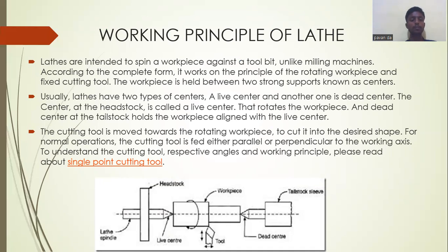The cutting tool is moved towards the rotating workpiece to cut it into the desired shape. For normal operations, the cutting tool is fed either parallel or perpendicular to the work axis. To understand the cutting tool, respective angles and working principle, please read about single point cutting tool.